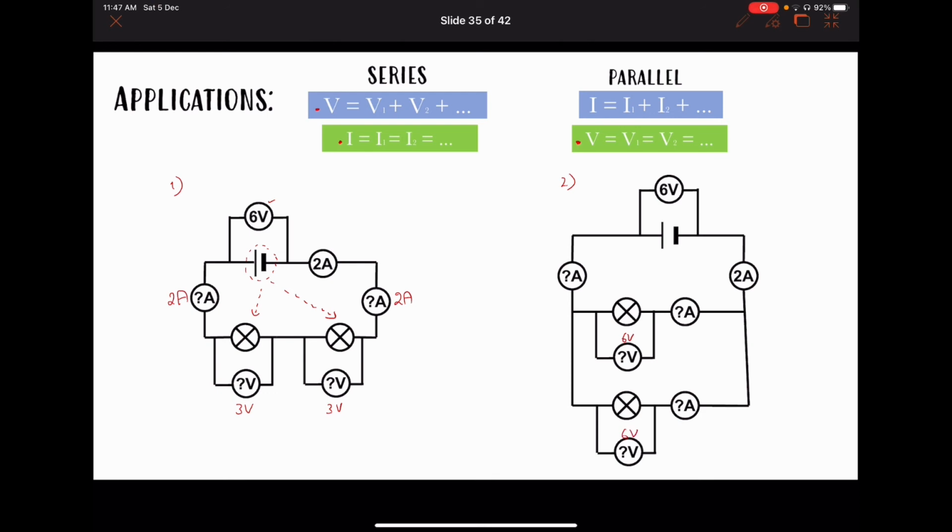All right, what about the current? The current is the sum. So if 2 amps are flowing in my main wire, then at this point, 1 amp will flow through the first branch and 1 amp will flow through the second one. And they will keep on flowing inside the wire until they meet again at this point and will merge again, adding up to get 2 amps.